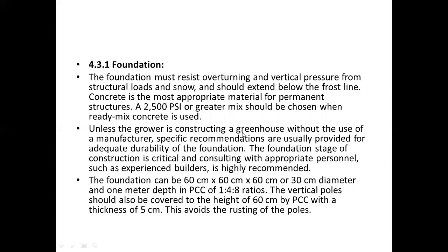PCC is plain cement concrete. Okay, and the ratio for cement, sand, and aggregate is 1:4:8. The vertical poles should also be covered to 60 centimeter from the ground by PCC with a thickness of 5 centimeter, which will avoid the rusting of the poles. Okay, so this was all about part one. Okay, thank you.